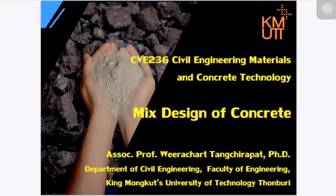Hello everyone. Today I will talk about the topic of mix design of concrete. In this topic, I will talk about the process to find the quantity of the raw materials used to produce concrete, such as cement, water, coarse, and fine aggregates, in order to meet two requirements: the first one is the slump of fresh concrete, and the second one is the strength at 28 days. The process to find the materials used to produce the concrete is suggested by ACI, or American Concrete Institute.